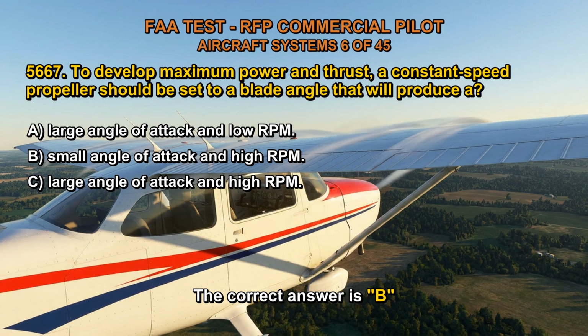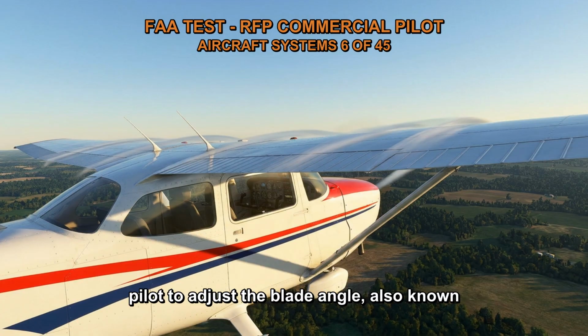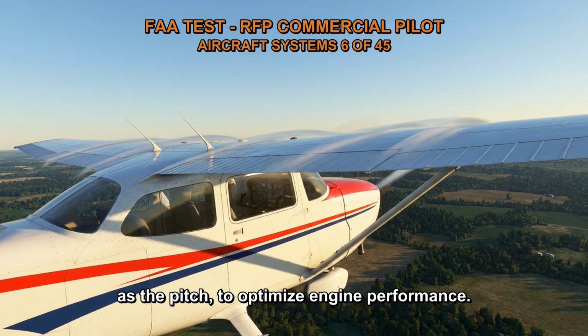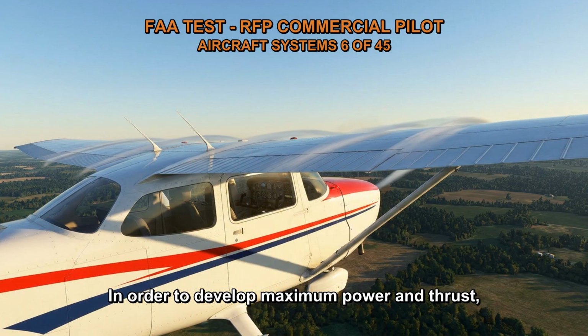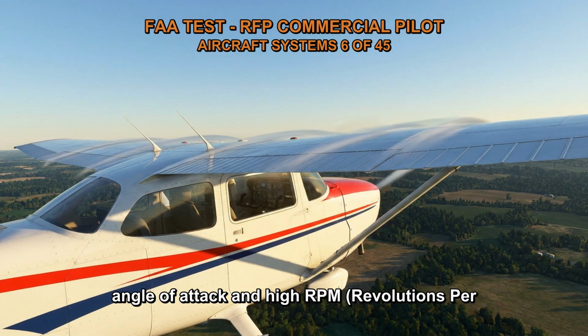The correct answer is B. A constant speed propeller is designed to allow the pilot to adjust the blade angle, also known as the pitch, to optimize engine performance. In order to develop maximum power and thrust, the propeller should be set to a small angle of attack and high RPM, revolutions per minute.